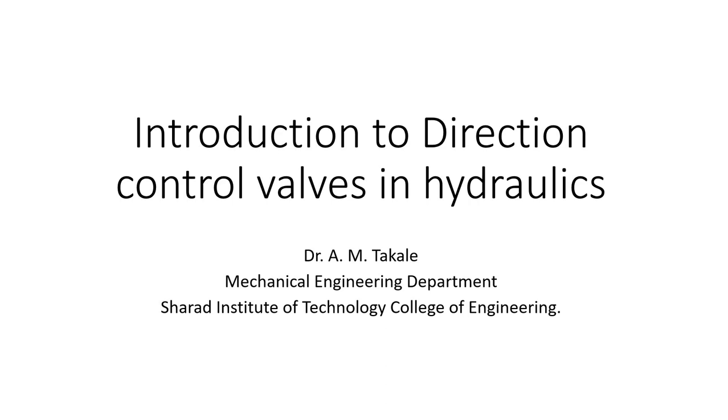From that pump, the oil is given to the main element, that is the direction control valve, and in between a pressure relief valve is fitted for safety purpose, and above that direction control valve there may be, as per our requirement, a flow control valve or a non-return valve, and above that a linear or rotary actuator. This is the diagram of a basic hydraulic system, in which in the middle there is a direction control valve, normally called a DCV, which plays an important role in hydraulics.